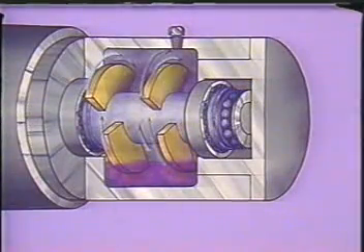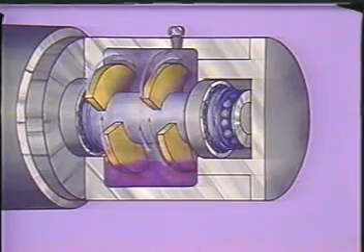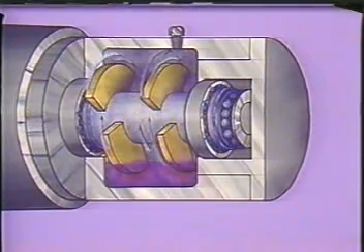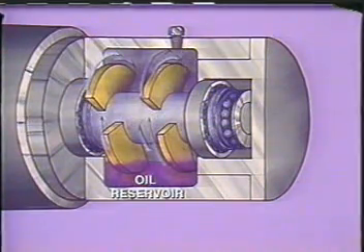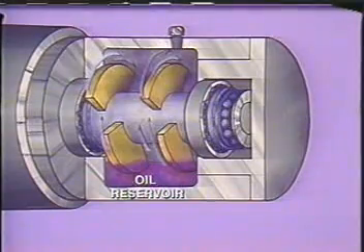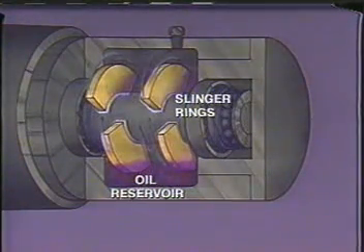The most important thing to remember about bearings is that they all need lubrication. Without lubrication, any bearing will be destroyed after just a short time of operation. These bearings are lubricated by oil, which is splashed onto the shaft by oil slinger rings as the shaft rotates.